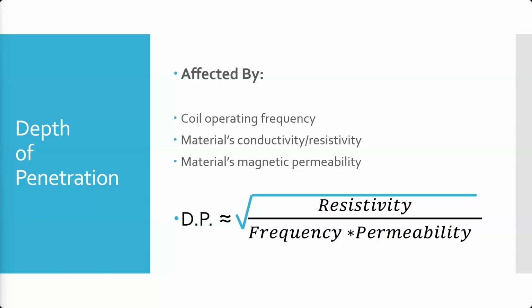And so something like that little pencil probe I was holding up is designed for surface flaws. This operates at high frequency, again, 50 to 500 kilohertz, 50 to 500,000 hertz. We have some bigger, this big coil probe that's 100 hertz to 1 kilohertz, lower frequency.